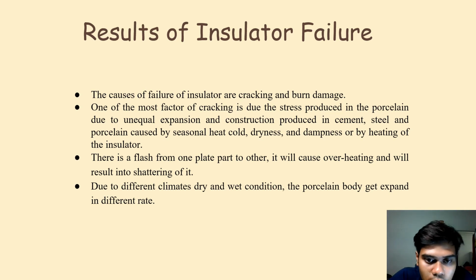One of the most factors of cracking is due to stress produced in the porcelain and due to unequal expansion and contraction produced in cement, plate and porcelain. It is caused by seasonal heat and cold, dryness and dampness, or by heating of the insulator. The next is there is a flash from one plate part to other. It will cause overheating and will result in shattering of it.